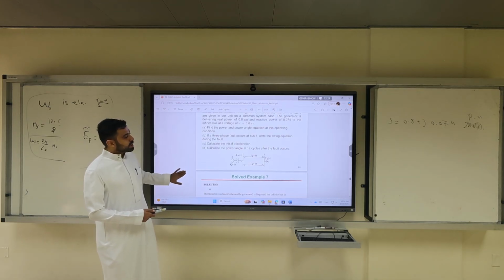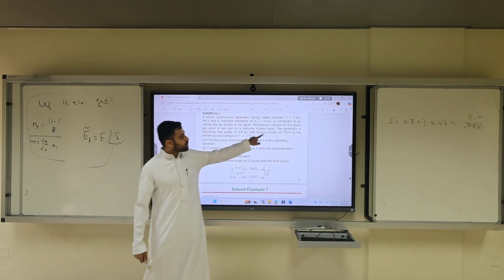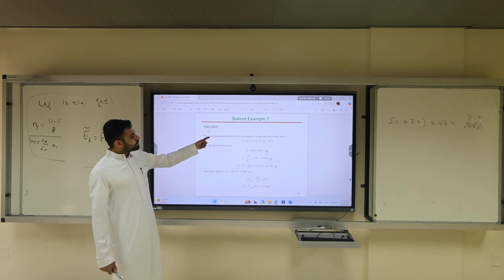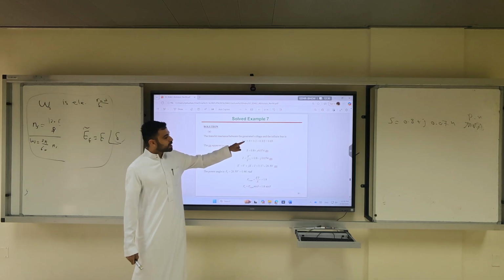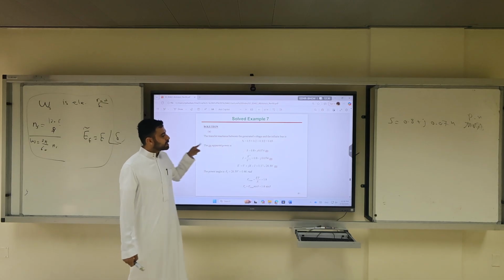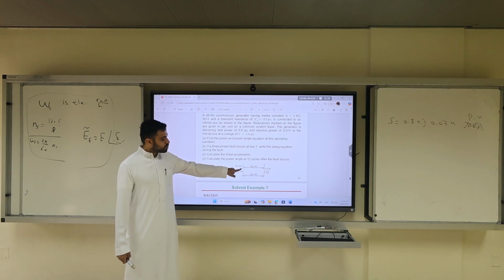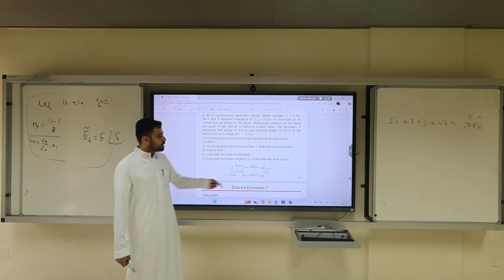So the power at the load is 0.8 plus j0.074. The transfer reactance between the generated voltage and the infinite bus, the whole reactance, is what? 0.3 plus 0.2 plus 0.15, which is the parallel combination between 0.3 and so on.